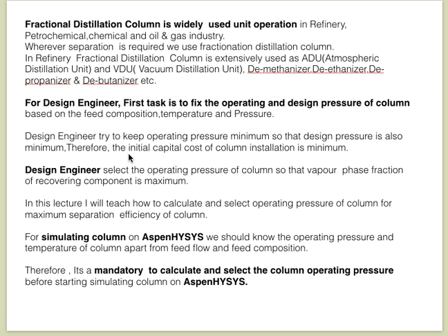For a design engineer, in any industry, the first task is to fix the operating and design pressure of the column based on the feed composition, temperature, and pressure, to start the design of the fractionation distillation column or the simulation in Aspen HYSYS or any other simulation software.